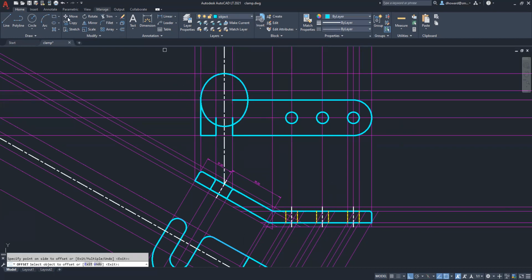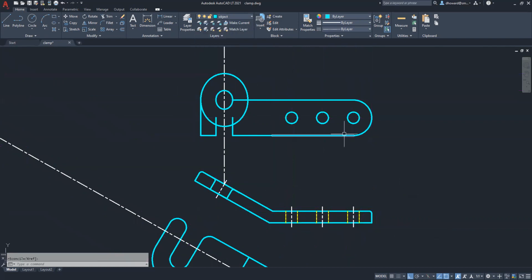Okay. And now I'm going to go to my ellipse tool and say the center is here and it goes from there to there to there. All right, so that distance again was 13 backward, and that's true size, so the widths, the top to bottom distances in this view are true size. It's the x-axis that's getting squished in this view. Okay, so things are looking pretty good here. Let's turn off the center construction lines and do a little cleanup.